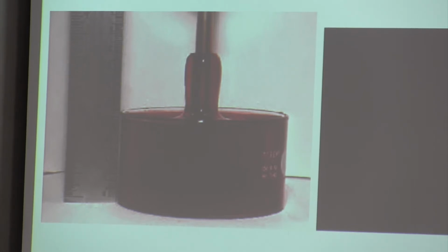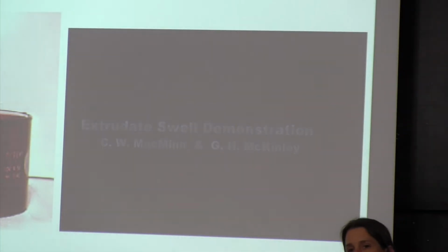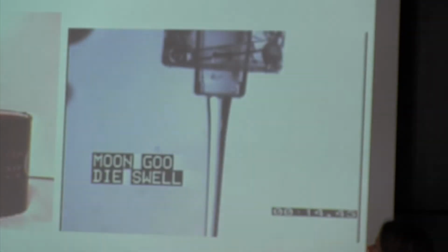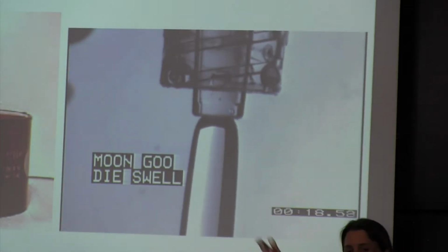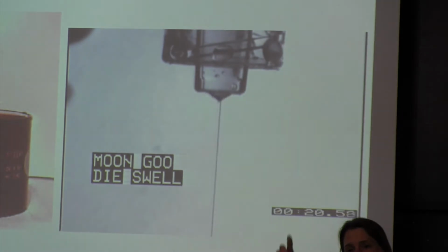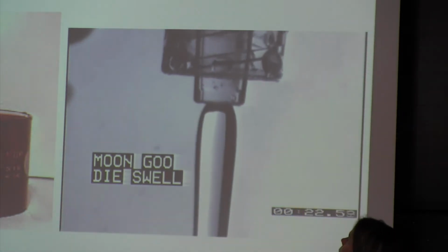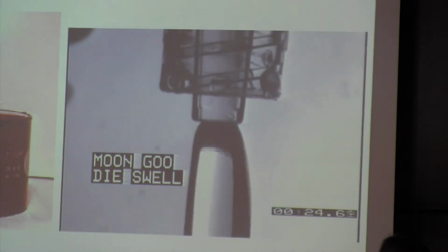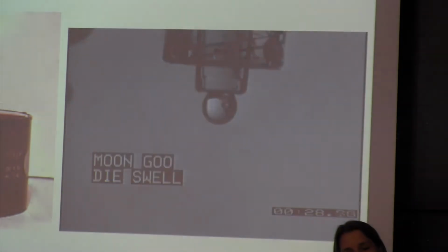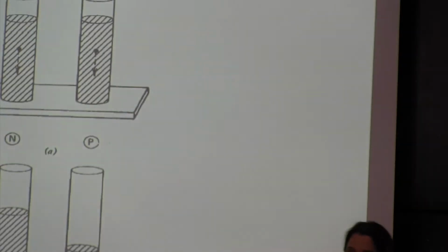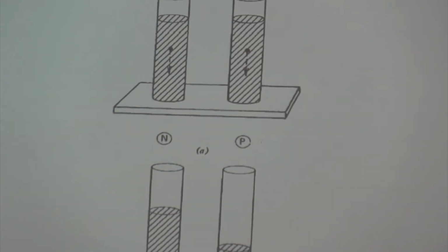Another effect that you might already have seen: for example, if you have shampoo under your shower and you press it very hard, when the shampoo comes out, it will actually, like you see here, not decrease the diameter, but increase the diameter once it comes out of the nozzle. So this is called die swell, and is also an effect of normal stresses, so additional tension in the direction of the streamlines. And then I will just finish with viscosity that depends on the shear rate.